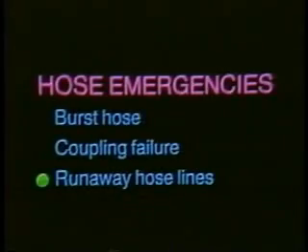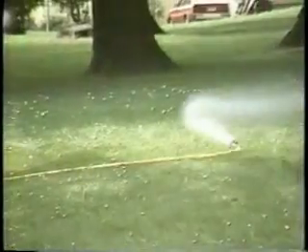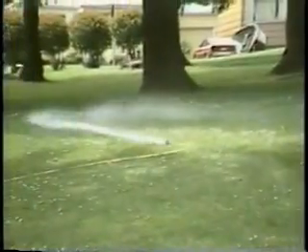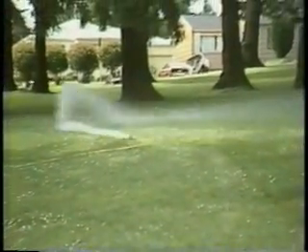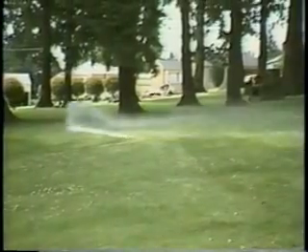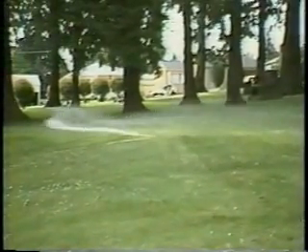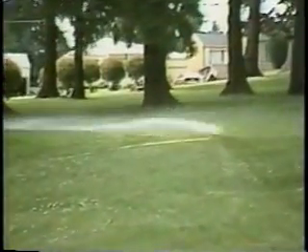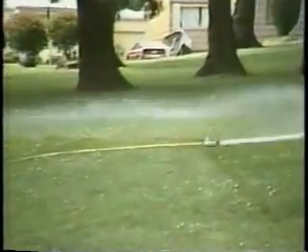Runaway or wild lines can kill as the hose whips back and forth. If a hose escapes you, retreat. If the pump operator can't be notified to shut the line down, if a hose clamp isn't available to stop the flow of water, and if bending the hose in half won't work, and if personnel are in danger from the wild line, then you can attempt to retrieve the line by slowly and methodically crawling up the hose toward the nozzle.